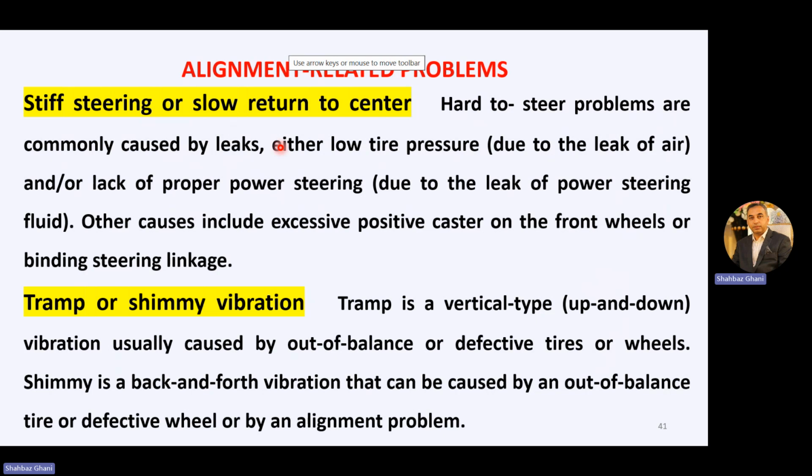So either there is a problem in your tire, that your tire pressure is low, or there is a lack of proper power steering, the fluid in the power steering is lower than the required level, or other causes include excessive positive caster on the front wheels or binding steering linkage. We will study these angles later on.